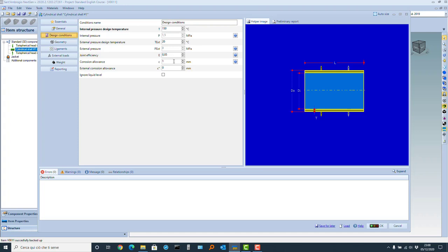There is no problem of plate tolerance because, according to ASME VIII Division 1 and also to Division 2, the plate tolerance must not be taken into account if the tolerance is less than the smaller value between 0.3 millimeter and 6% of the thickness. In our case, as all ASTM materials, the tolerance is 0.25 millimeters, so it has not to be taken into account. The thickness is 18 millimeter. The diameter of the shell is 2.5 meters, and the length is 6 meters.